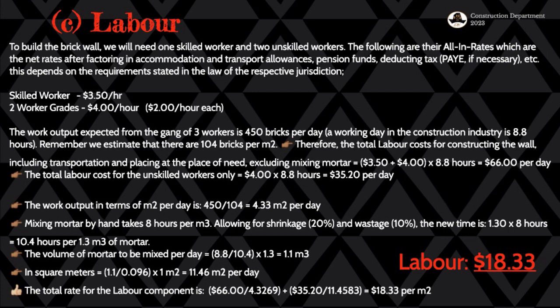And then for the volume of mortar that is to be mixed per day, we say the 8.8 hours divided by the 10.4 hours of mixing the mortar, because 8.8 hours is the hours per day that we expect the workers to work. But we then have the 10.4 hours for just mixing the mortar, my apologies for that, and then we multiply that with the volume that they are going to be mixing, which is the 1.3 cubic meters, and then we get our answer, as you can see right there.